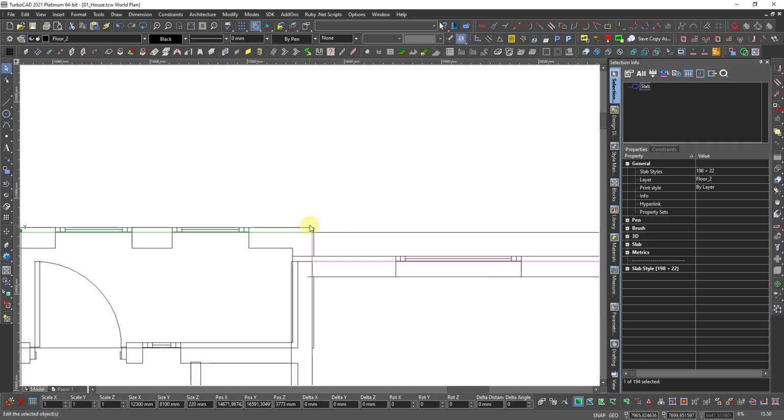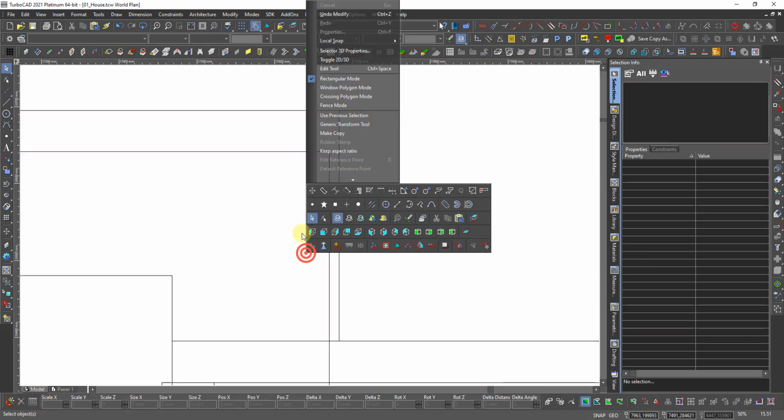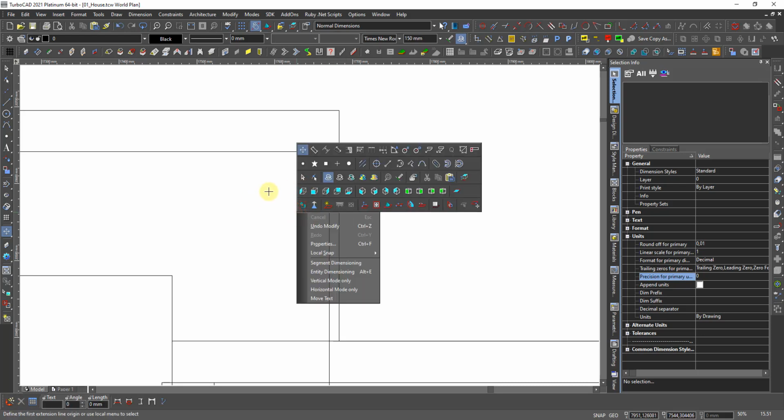This is the slab. And the slab does not follow this 54 line here. This should go 54 in this way, like this and like this. That's correct. That's wrong here. I can see from nearest to nearest there's 13 millimeter. That means I need 54 minus 13, which is 41.